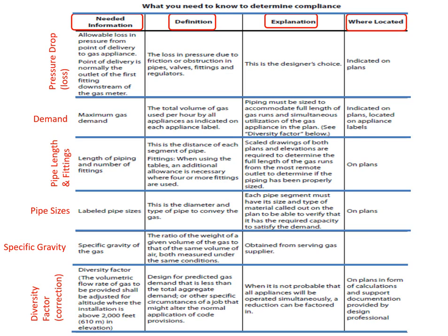Number one we're talking about is the pressure drop. Pressure drop is very important. We need to understand what the pressure drop or loss is so we can overcome those pressure drops simply by increasing the pressure, increasing the pipe sizes and fittings together, things of that nature. So many different options of the designer, but we need to understand pressure drop.